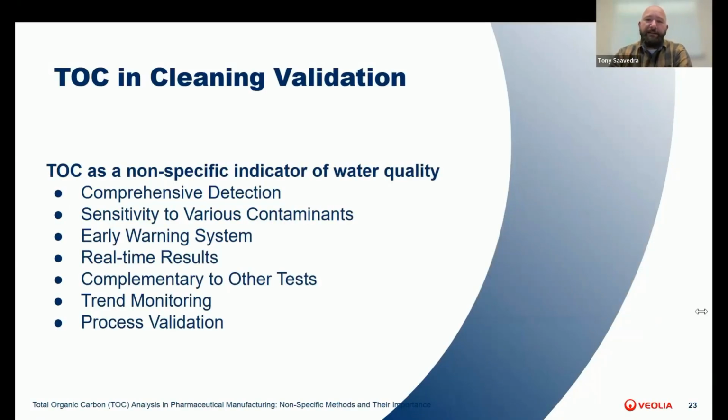Let's discuss why TOC is such a valuable non-specific indicator of water quality in pharmaceutical manufacturing. There are several key points to consider here. First is comprehensive detection. TOC analysis provides a broad overview of organic contamination in water. It doesn't just look for one specific compound. Instead, it detects all organic carbon present.